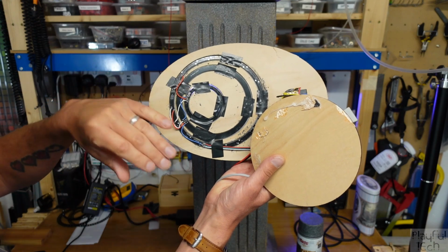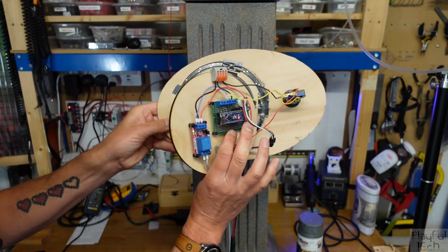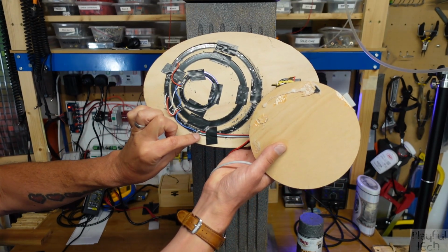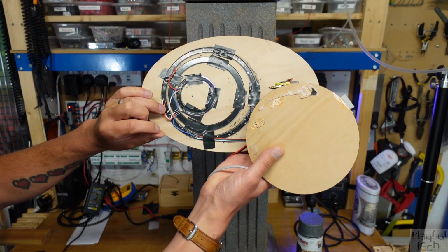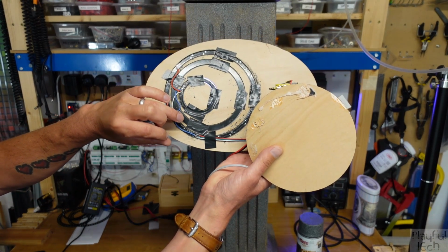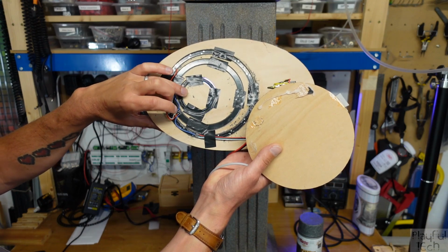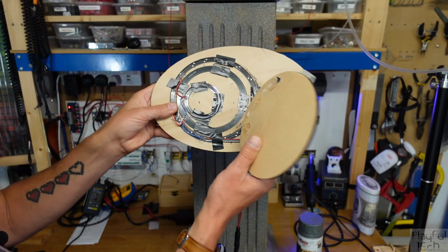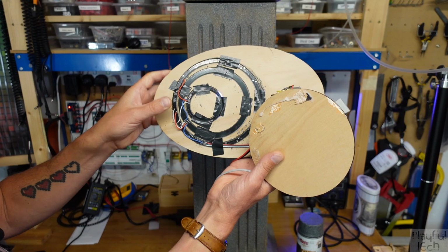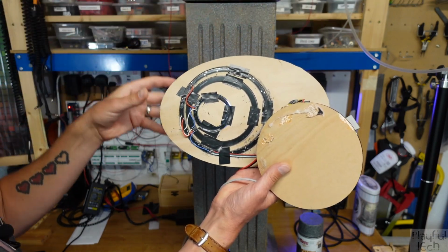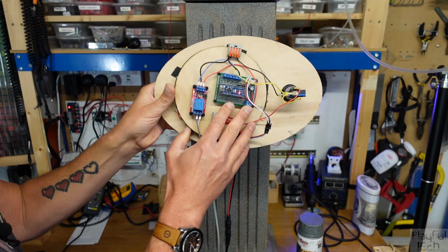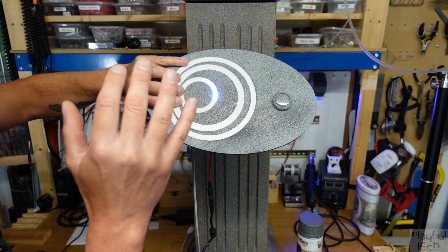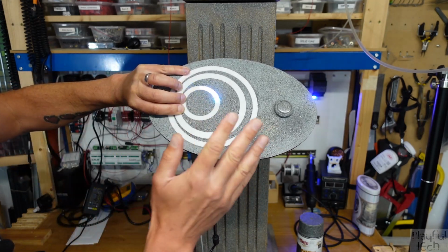And the way I've got them wired up is that I've got a single pin of the Arduino wired into the data in of the outermost ring, and then I've got the data out from that ring going to the data in of the next, and the data out from the middle ring going into the data in of the innermost ring. So these are all wired in series, which means as far as the Arduino is concerned, this is effectively one single continuous straight line of LEDs. The logic that separates them into these 3 different rings is actually all handled in the code, which I will show you in a moment.